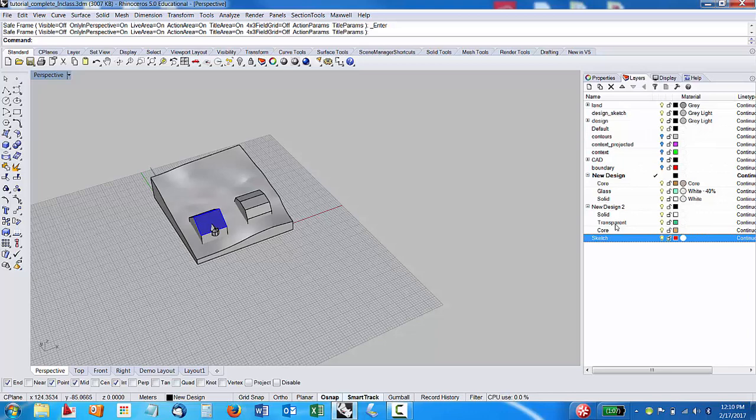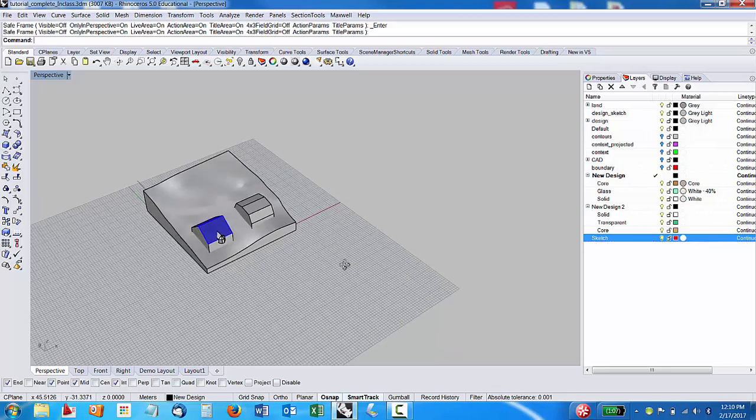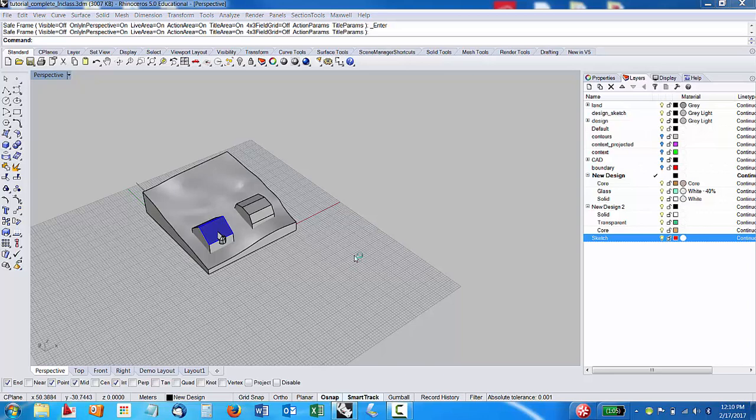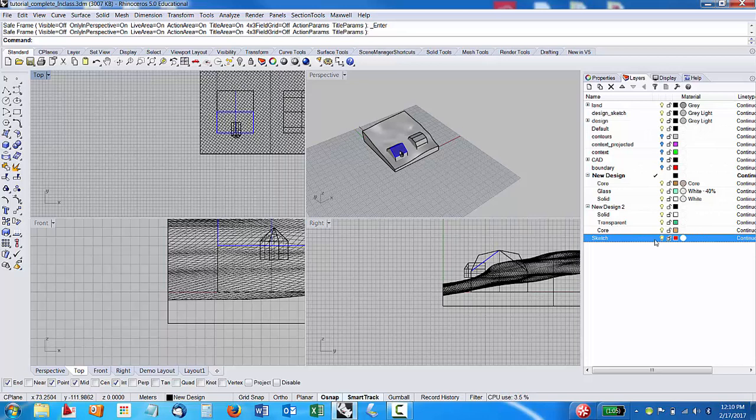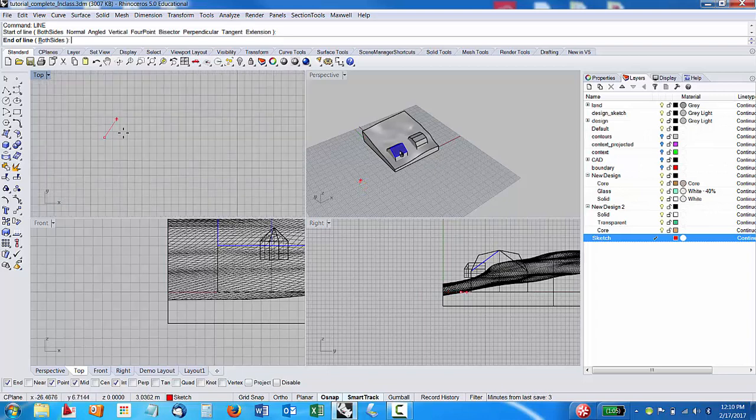But what I'll do first is I will maybe just make a little object to draw. So, I think Emmanuel was maybe talking about structure, right? So if I come to my viewports here, I can start, say, with my sketch layer. So I double click that, and this is in meters. So I'll maybe make, and I'm going to put ortho on by hitting O. So now I'm only drawing in this direction.